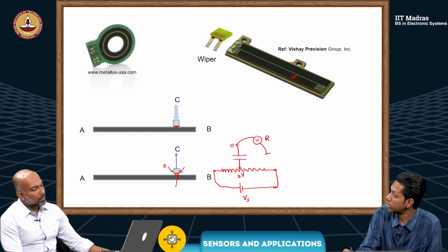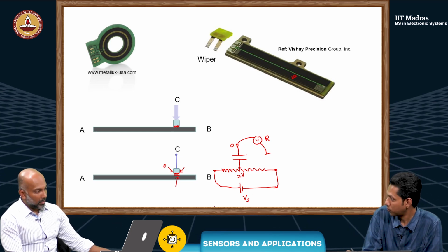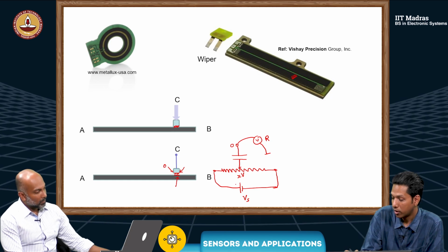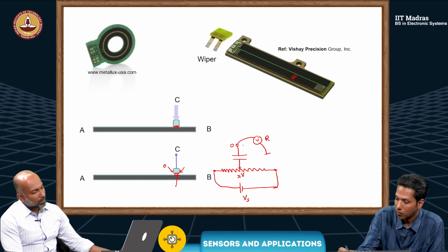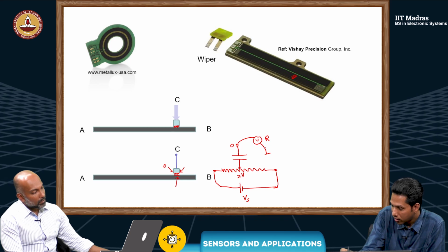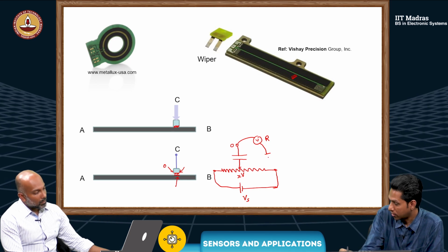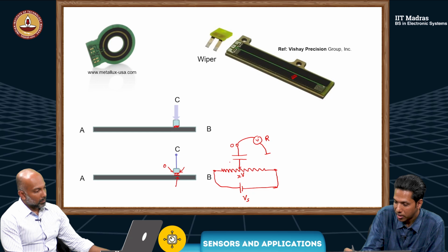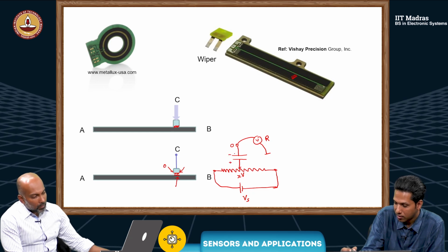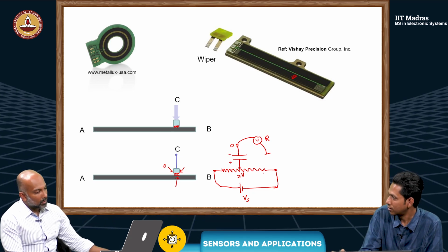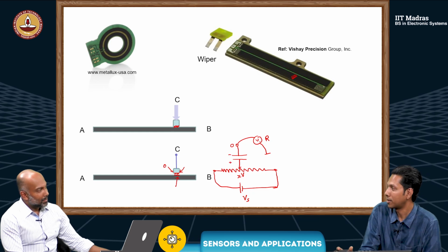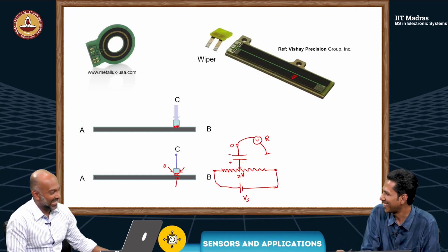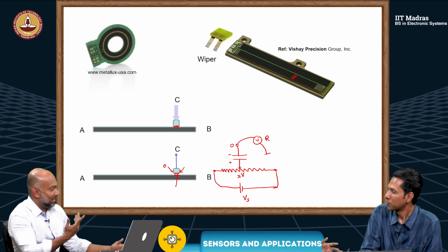So depending on the position of X, there will be an X volt there. Correct. It's a DC voltage. So this capacitor is now connected to ground through this resistor. Right. So basically it will charge to this X volt. Yes. And then finally the voltmeter reading will be 0. Correct. Yes. The capacitor charges.